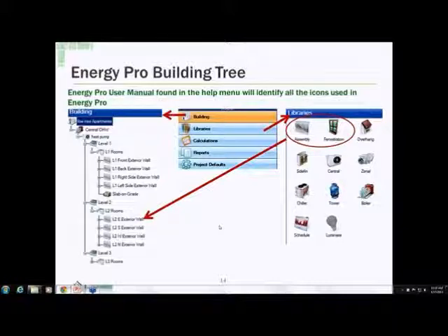Okay, there are many things that don't run in low-rise residential but do run in high-rise residential. When you're doing a low-rise residential calculation and a high-rise residential calculation, you have to understand that you're using two different energy code compliance metrics, one for residential and one for non-residential. As far as the components go, all of the assemblies are going to stay the same. The systems are pretty widely different, and so are the calculations. So we're only going to be looking at the building envelope and what the calculations can do for the building envelope.